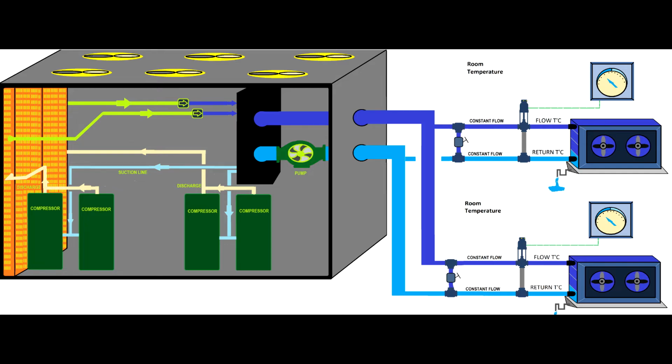They go into this orange condenser, and the refrigerant is cooled in the condenser and liquefied. Then it continues its journey through these green pipes, subcooled, to reach these expansion valves, and you'll see these little yellow arrows that are pulsing.